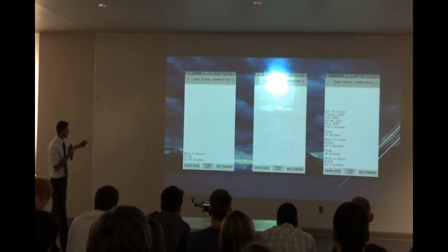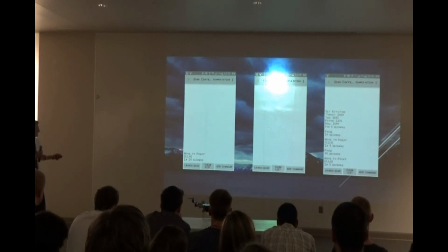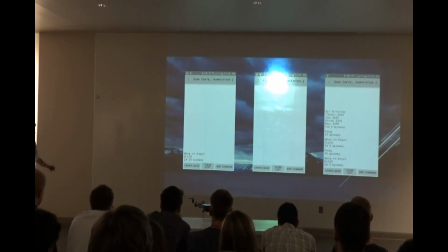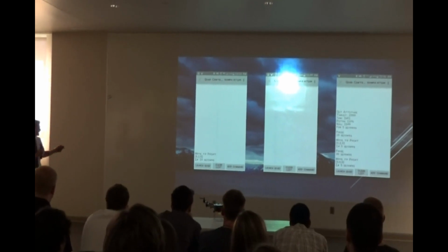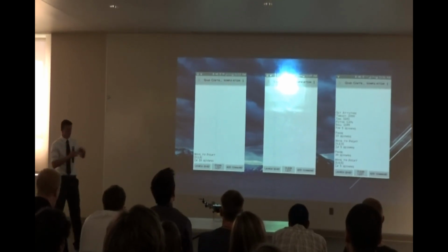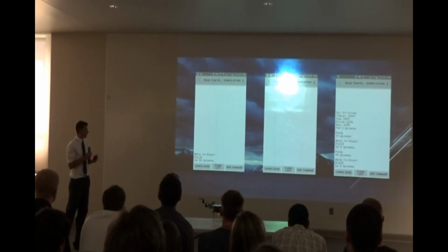So here, I just started a mission and just created a basic point-to-point. So it's going to tell the quad to move to a point, and that point would be a Y value of 1 foot, so it would raise 1 foot off the ground, and I want it to be completed in 10 seconds. So now if I were to say, launch the quad, the Android would then tell the quad what to do over Bluetooth.